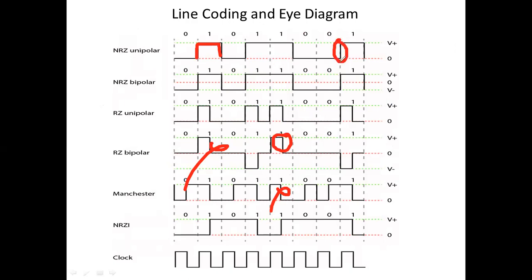And you see, you might have sent a wave which is something like this, but the moment you give an input like a sudden change, it is always resisted. You end up getting something sluggish, right? The moment you give the input which is something like this, the output doesn't follow, right? The output takes a lot of time. Zero crossing, then again your input has come here, then the input suddenly decays. Then this one takes a lot of time to even decay. It depends on your channel's impulse response, it depends on the time delay spread, right? There are so many issues that are going to occur.